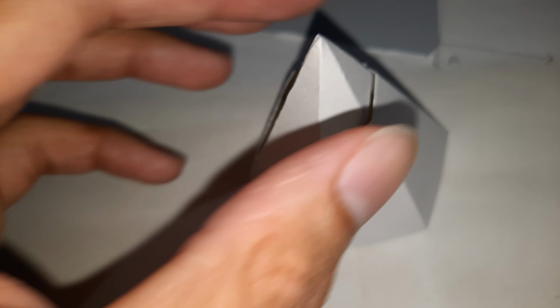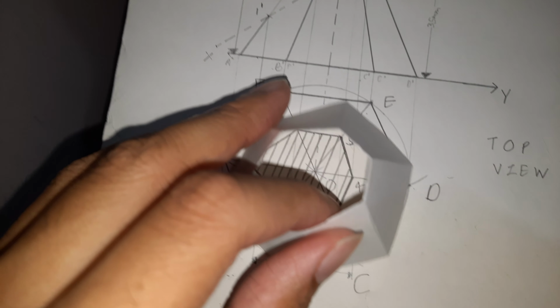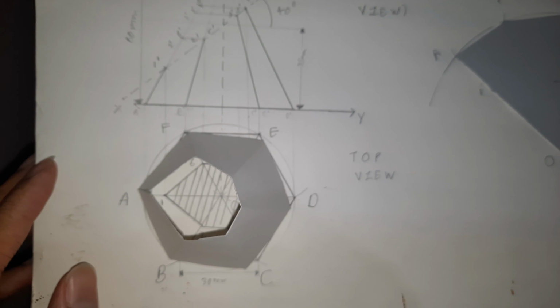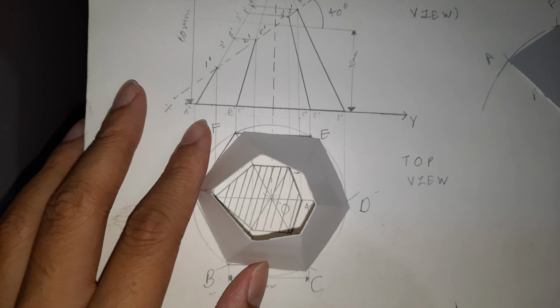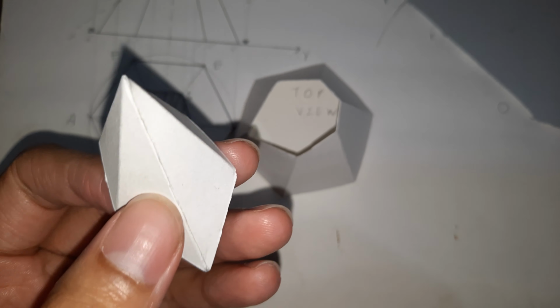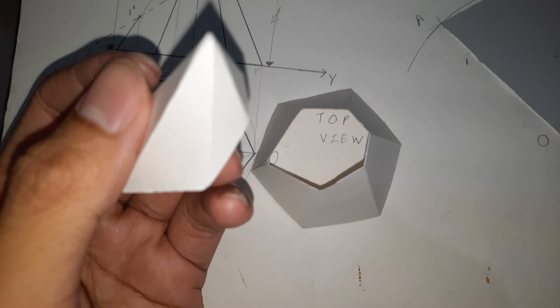After cutting by the AIP, this much part of the hexagonal pyramid is remaining. We can check here. Almost the same section we are getting. Sorry for the bad angles. So this we are getting, and we got it by cutting the hexagonal pyramid by an auxiliary inclined plane. This is the plane, something like this, and we have chopped this and we got this as a result.